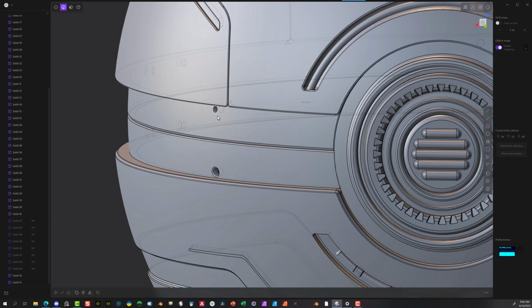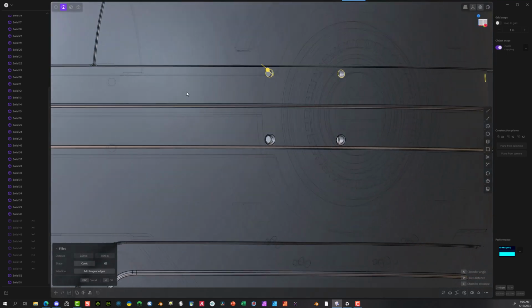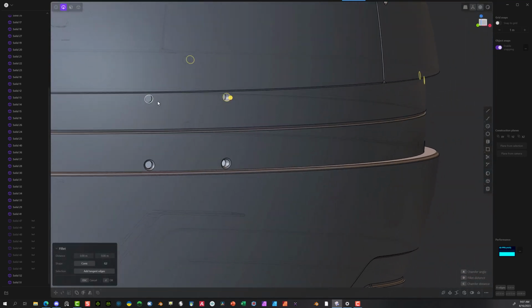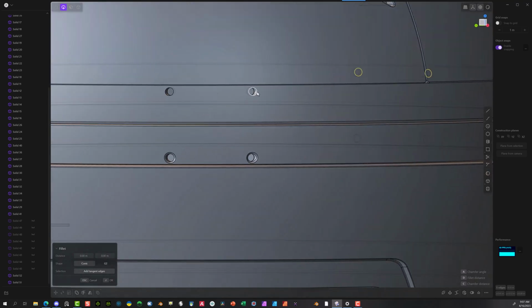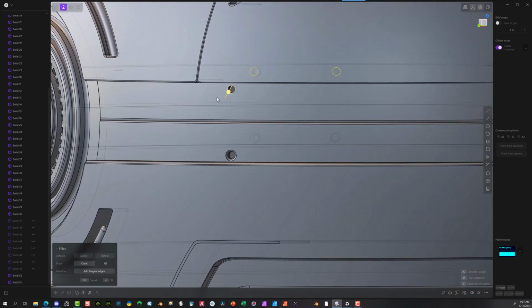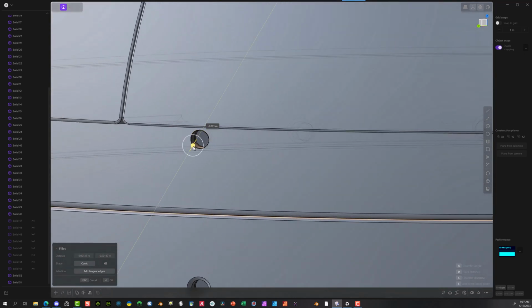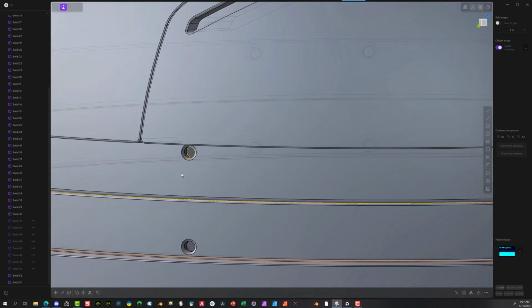This time, select all these again. Keep hitting Shift key as you go around. Okay. Got 8 of those. Again, chamfer. I'm going to go ahead and select it now. Put Control V. Control V. Hit Tab. It's exactly the same as the bottom.